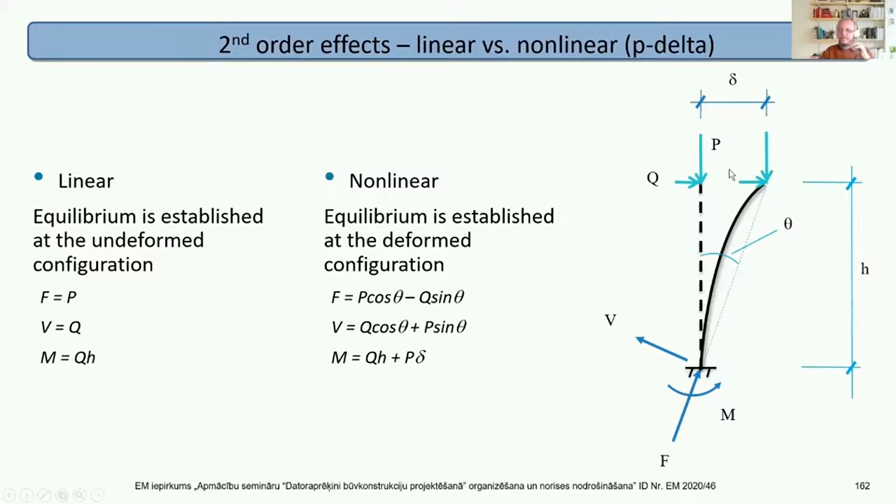And watch out for anything more than a very tiny deflection. The P-delta analysis can give you quite strange results. So in general, if you're thinking about doing a P-delta, I would go for a non-linear. P-delta can give you a check on that, but P-delta is a sort of cheap non-linear analysis. It can help sometimes, but not always.